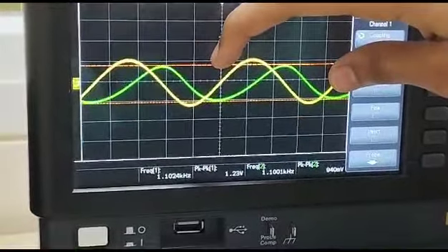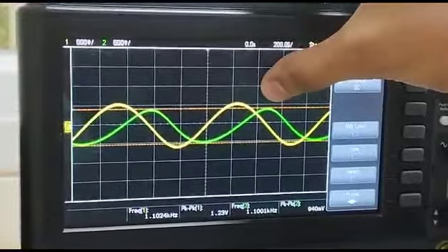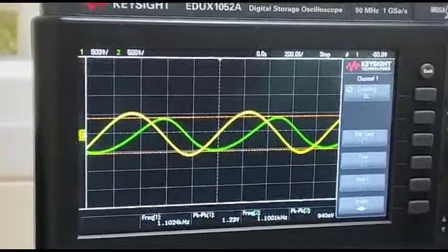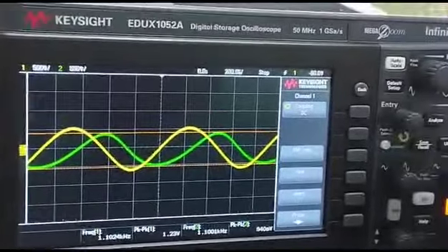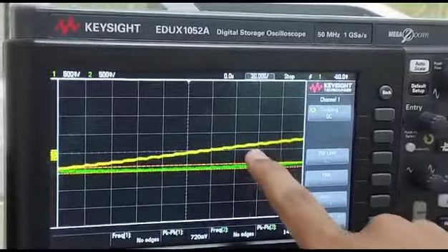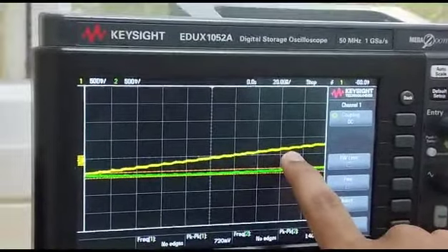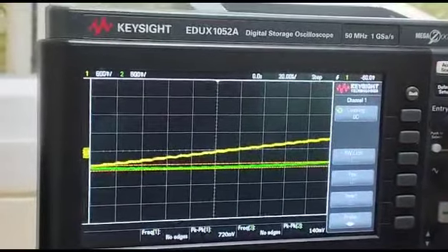The lower frequency part, which is f1 minus f2, is only observed in the output, whereas the component of the other frequency is completely attenuated, but you can still observe slight parts of it when you zoom into it. These slight peaks are the components of high frequency, which are reduced when compared to the previous output which you observed through the mixer.